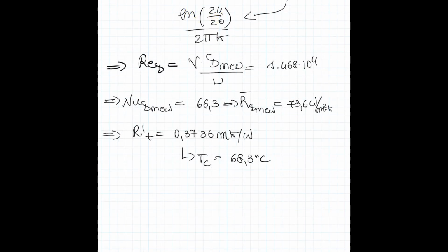Now, you can see that the conductor temperature has increased with the insulation. Therefore, we can say that the polymer insulation layer is added to improve the electrical insulation of the system and therefore also its safety. Indeed, if cables touch after the insulation layer has been added, there won't be any electrical interaction, or it's not going to be as strong as before. However, this comes at the cost of increasing the thermal insulation, and therefore it has bad consequences on the temperature of the cable. So as engineers, you must remember that electrical insulation is not the same as thermal insulation.